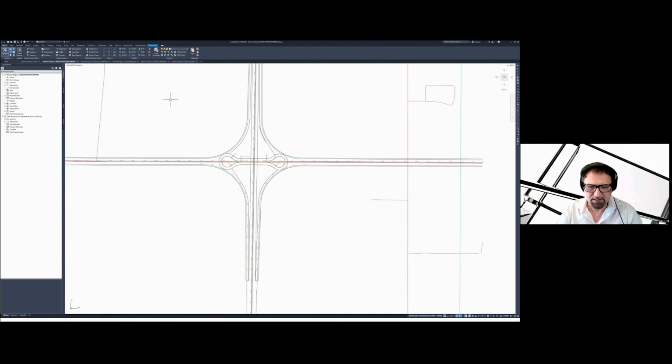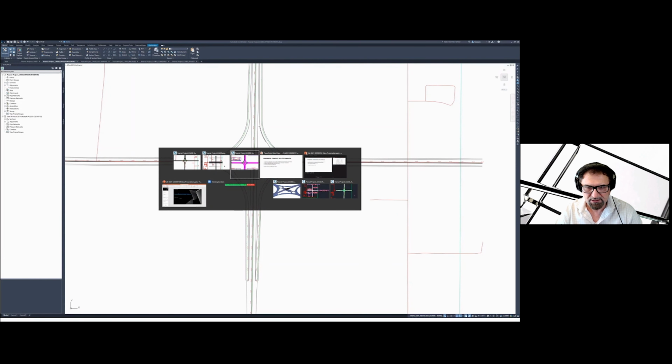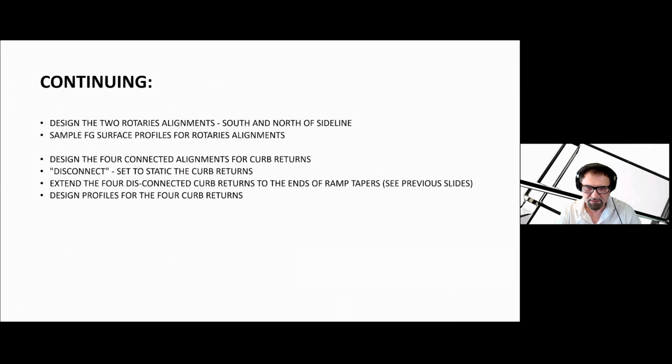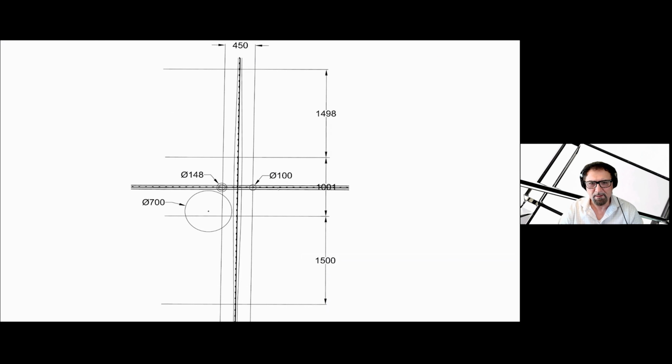Clearly, like I said in my slide, let's go take a look at that slide again. Oh, I didn't size them, I think. Yes, I did. So the inner circle for those two roundabouts has a radius of 50, and the outer is 24 feet more, so it will accommodate 2 lanes. So that's 148 feet radius. And then for the on and off ramps joining this widening, we're going with 700 feet or 350 feet radius.